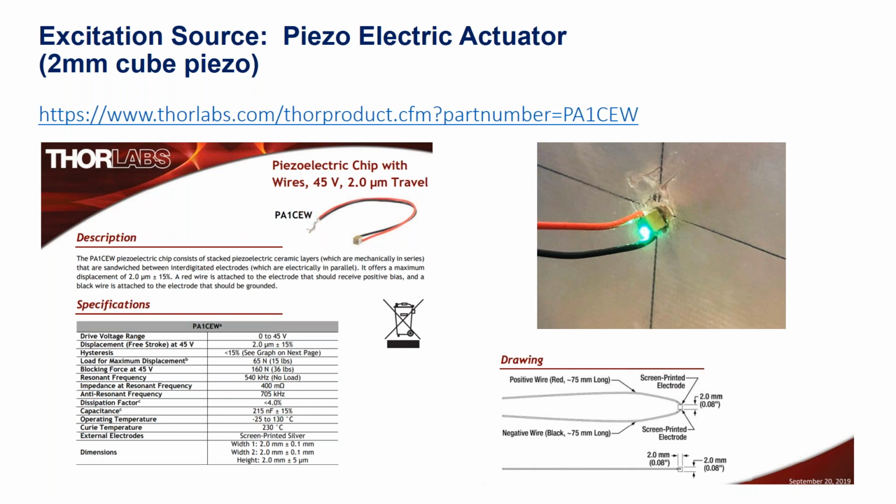We just glued it right under the surface at the location I described. And then you're able to vibrate from that component. So by putting voltage through that, you have the piezoelectric effect. This vibrates that object, and that was our source of vibration. That's how we excited it. And what we tried to do was mimic a buzzing component.